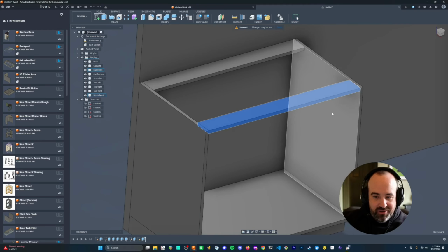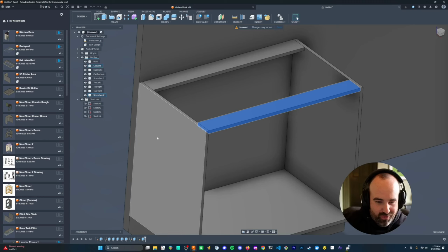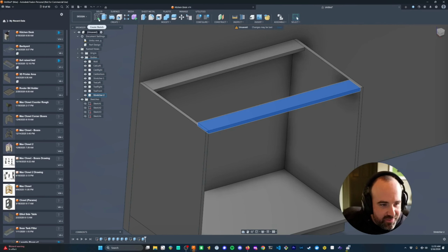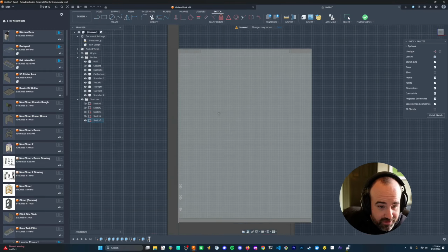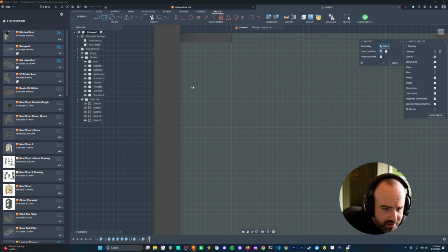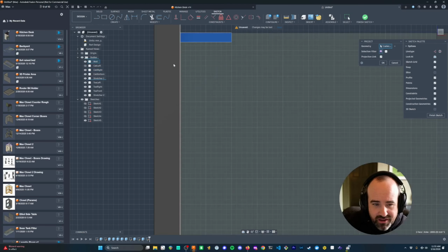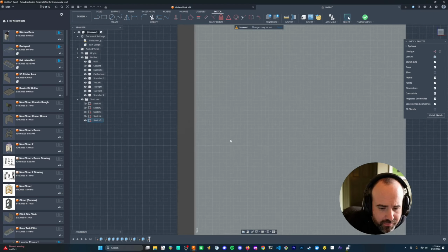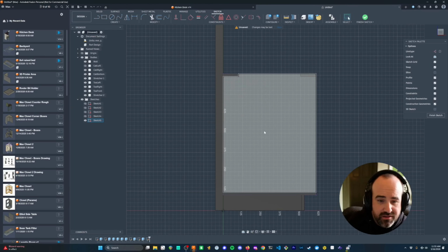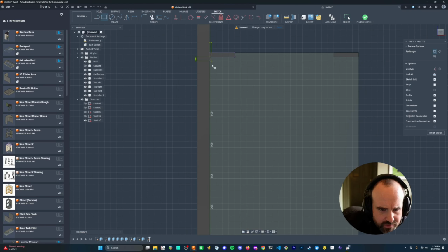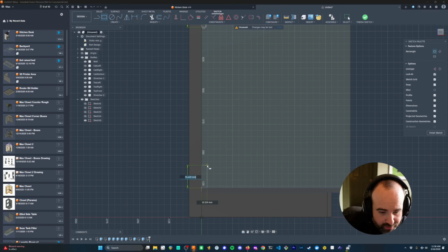And I'm going to do a similar thing for the nailer in the back. That just gives us a way to secure it to the wall. You can do one or two nailers, I guess, depending on how secure this needs to be for you. I'm going to do two nailers. I'm going to go here. I probably have to do some projection so I can get a nice corner to work off there, and then one on the bottom and project this. I'm going to use the same stretcher width value, ply thickness, and do one on the bottom too.